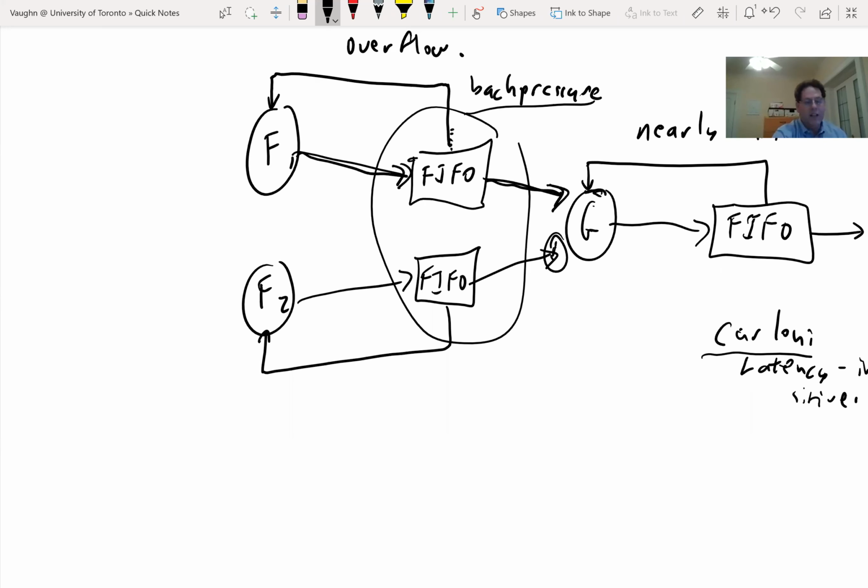So it depends on the latency to stop G. And so that latency might be 1 cycle, in which case we only need 1 item left in the FIFO when we assert nearly full. But inside G, we actually have a lot of control. We know our computation, we know all our inputs have arrived, and so on. So inside G, we might use a less flexible model.